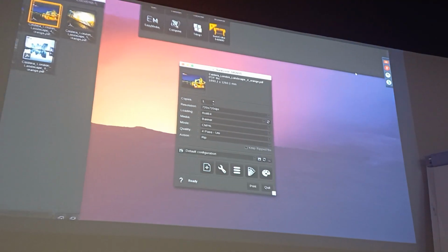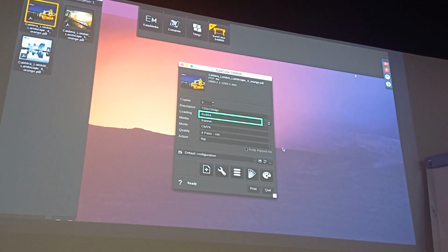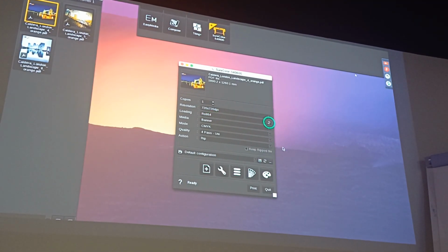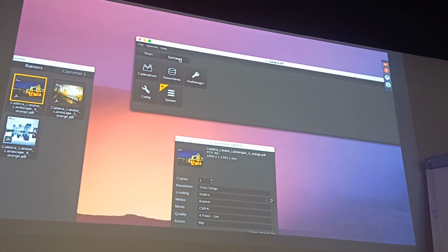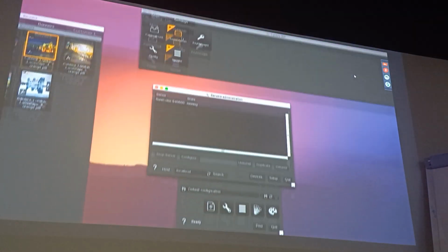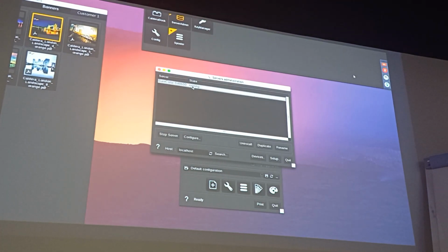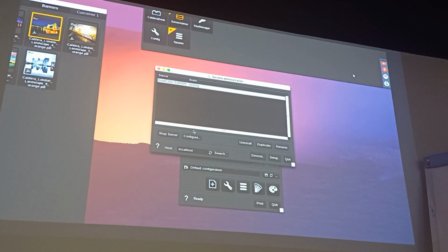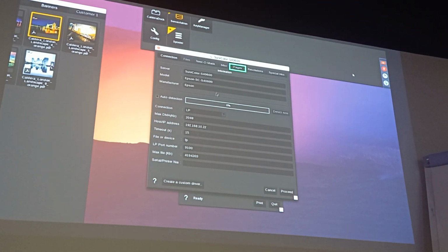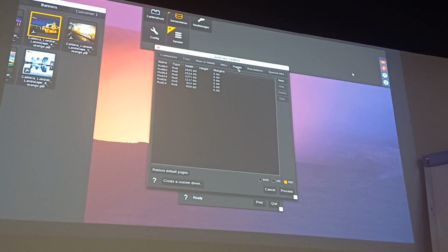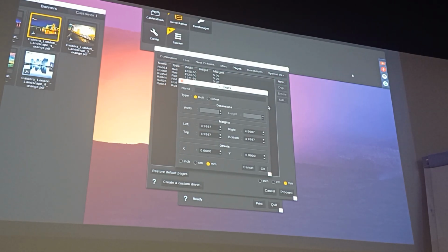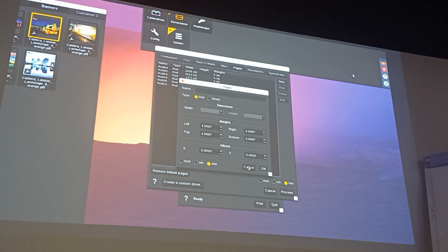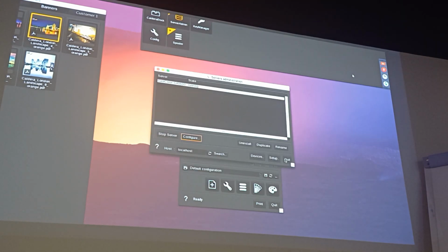Let's choose a roll 64 inches from the loading menu. You can also synchronize with your printer to get immediately the correct format. If needed, you can create your own format by going in Server Admin. In the Printer Configuration tab, you will find a Page tab where you can create and store custom roll or page sizes. After saving the modification and restarting the driver, your custom format will be available in the print module.